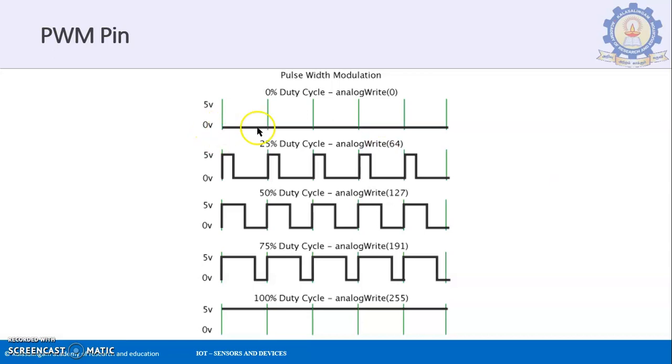Okay, so this is 2 milliseconds over here. You can do the small calculation over here. It is 1.5 milliseconds over here, and this is 0.5 milliseconds over here. For 0.5 milliseconds it is going to be on, for 1.5 milliseconds it is going to be off. You will not be able to see that 1.5 milliseconds of this particular signal being off. By that time again the LED will get charged, then again it will discharge, then it will get charged over here. So you will be able to see the LED with the brightness of 25%.